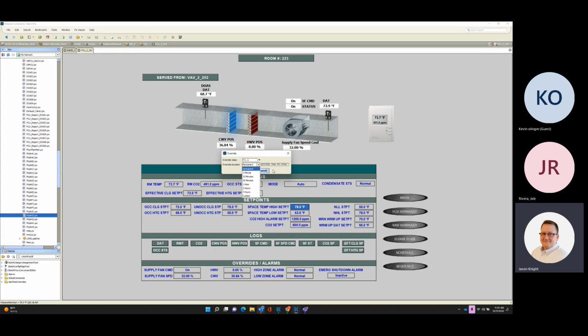Or maybe you just got a customer that is not comfortable at 73.5 and you just need to make that person happy, and override the set point or set the set point a little bit cooler and then override your alarm limit. But anyway, it's just about as customizable as you can make it. You have your morning warm up set points, your morning warm up discharge air set point for the unit, your night high limit, night low limit, pretty standard from what you guys are familiar with from your other buildings, for just a generic fan coil or air handler.